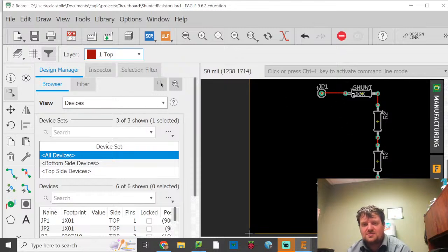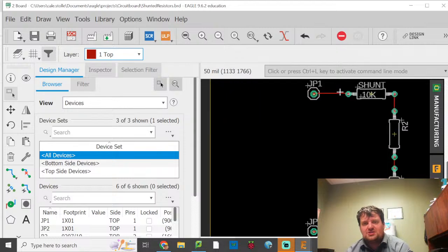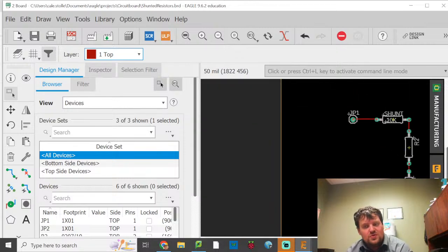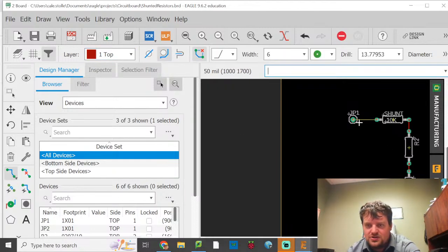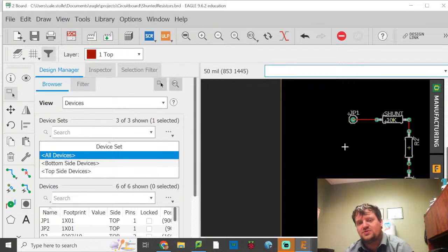Now, if you have some schematic where when you hit the auto router, some of them have to be blue, that's okay, because it just means those wires are going to be printed on the bottom side of the circuit board. The issue is you got to make sure that none of your red wires cross and none of your blue wires cross. You want them all to be as straight as possible. You may have to manually go in and delete a wire, so I may have to click on this red wire, hit delete, and then I may have to do a route myself where I connect terminal to terminal. Okay, and that's ultimately how you would do that. Pretty simple. You give intermediate clicks to say here's where I want my intermediate positions to be.